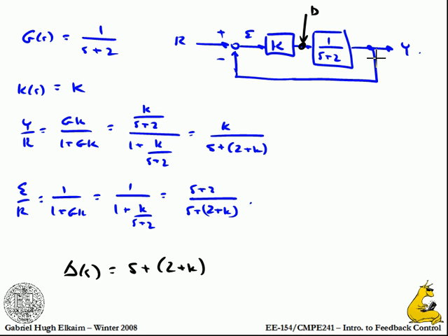All right. We're looking for the roots of the closed loop system. The roots of the closed loop system tell us how the system is going to respond. What we're doing to find the roots of the closed loop system is we're saying look for where the open loop system, gk, is equal to negative 1. If I can find where gk is equal to negative 1, then I'm at a place where I'm at the roots of 1 plus gk. And remember that the roots of the denominator tell me how I'm going to mix together my final response.